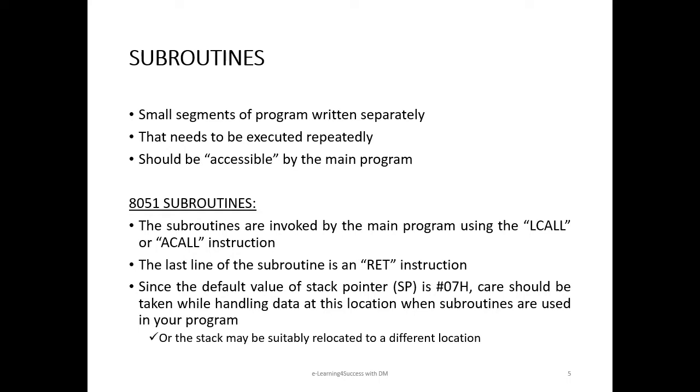One should be careful about the data in stack and register banks while using subroutines in 8051 microcontroller. This is because the reset value of the stack pointer is 07H. A suitable method is to relocate the stack to a different memory location.